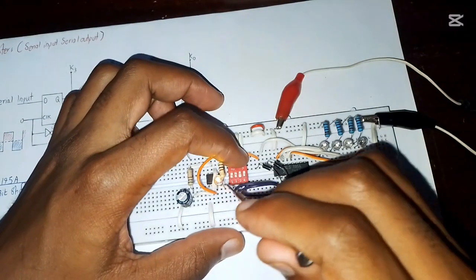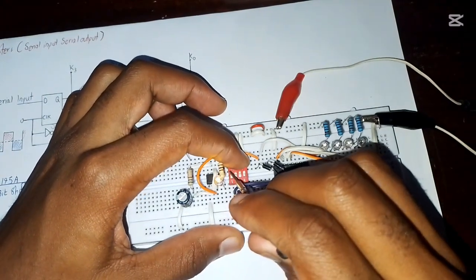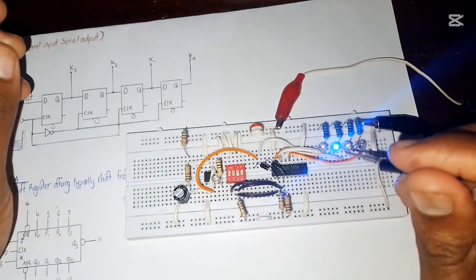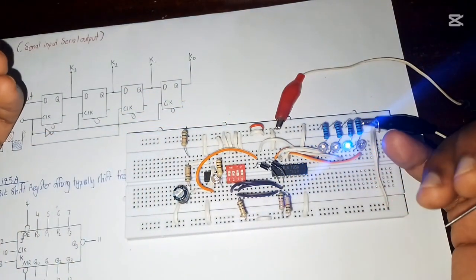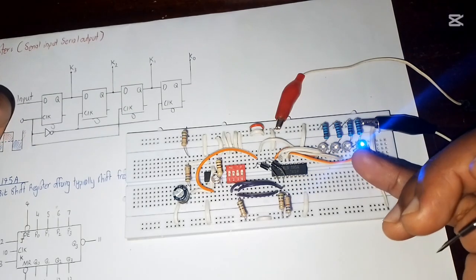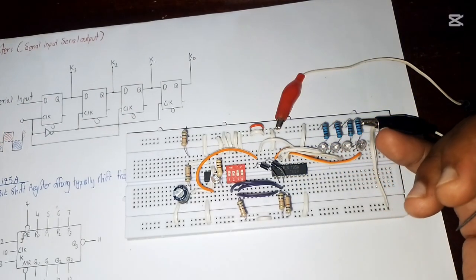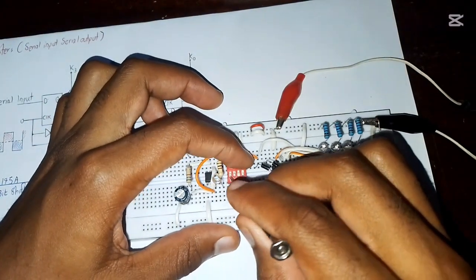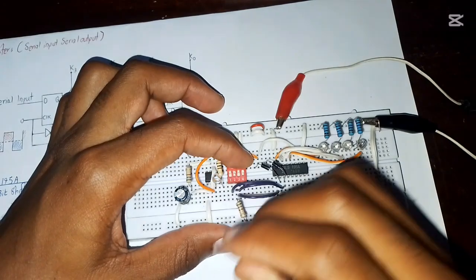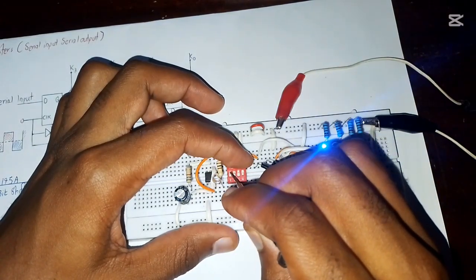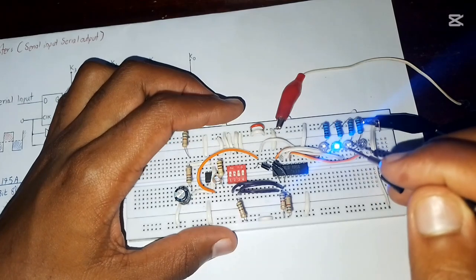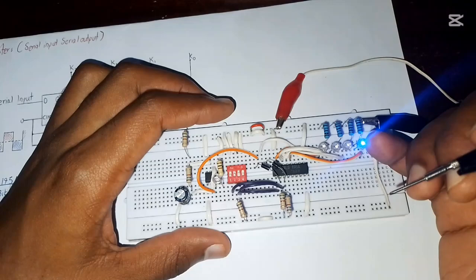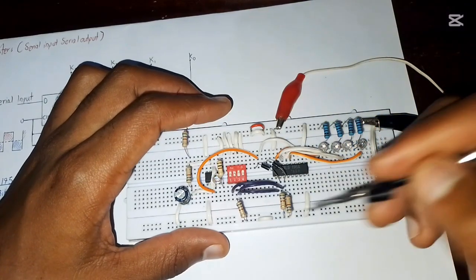If you can remember, we said there's a serious drawback of the serial input serial output, which is that you have to wait for those 4 clock signals before you start receiving your data. You can see after those 4 clock pulses is when you're going to start receiving your data. So that's a serious drawback of the serial input serial output connection. So we do that again, put 1, then I'll turn it off. That one goes from flip-flop to flip-flop, and you have to wait until those 4 clock pulses to start receiving your information. So it's a 4-bit.